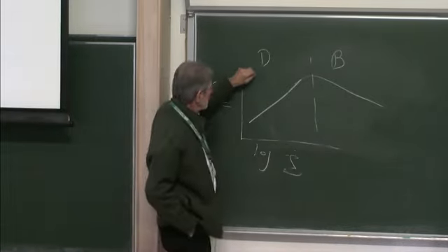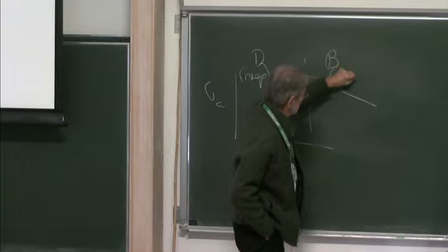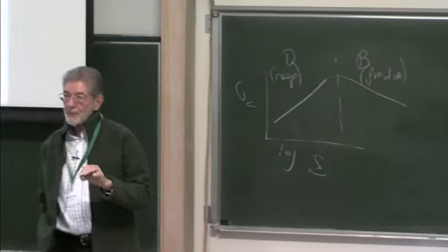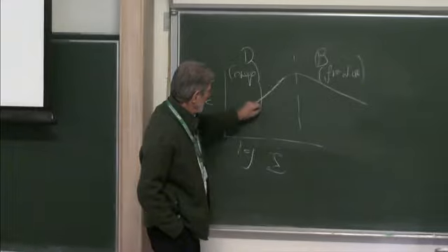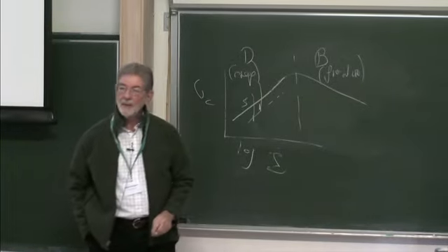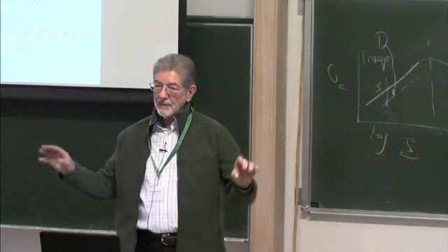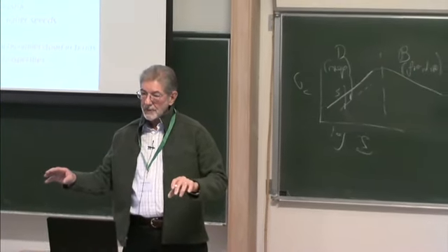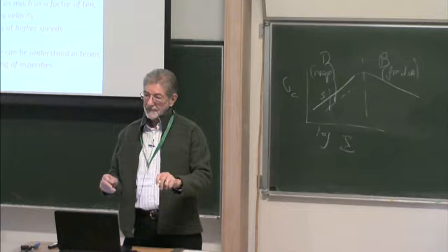Ductile behavior creep, brittle behavior fracture. Okay? Within the low speed creep regime, the strength decreases with increasing salinity. Saltwater ice creeps more rapidly than freshwater ice. The higher the salinity, the greater the rate of creep, or for a given rate, the lower the compressive strength.